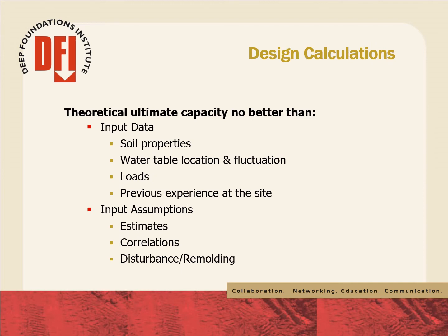Theoretical capacity models depend on accurate soil properties, tests, and experience. Theoretical models usually depend on soil strength correlations, estimates, and disturbance factors related to the means and method of helical pile installation.